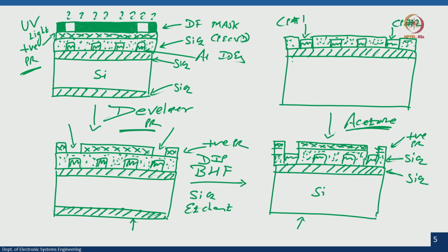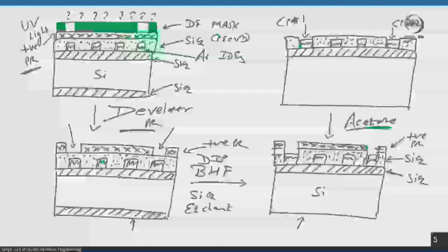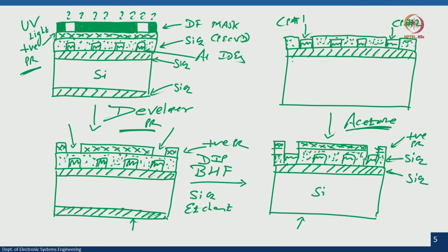All right. Now, I hope that you understood how to deposit a metal, how to use the lithography system or process, and with that how to pattern it. If I want to go for silicon dioxide on metal which is having a lower melting point, then PECVD or sputtering is better. And if I want to open the contact pad, how to design the mask and how to expose it and what are the process. So, with this I will stop it here.